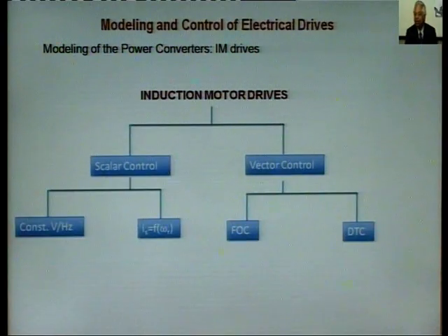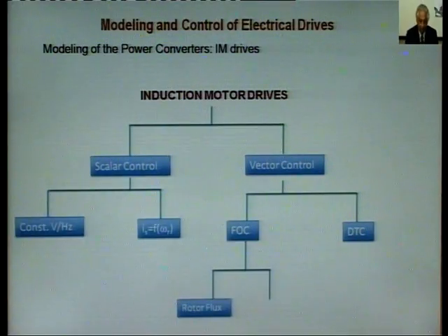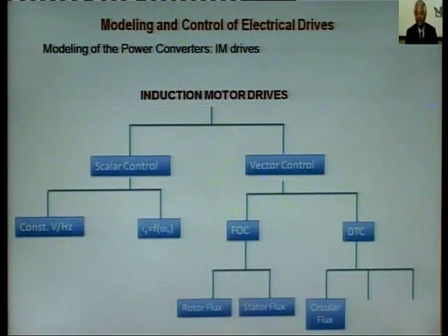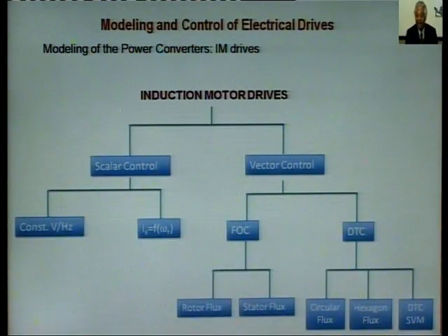So, there is direct torque control and field oriented control. FOC can further be classified as rotor flux and stator flux. You have 2 types of flux, one in the rotor, known as rotor flux, and another in the stator, known as the stator flux. DTC can be further classified as circular flux, hexagonal flux and DTC SVM. So, this is what the induction motor drives are.